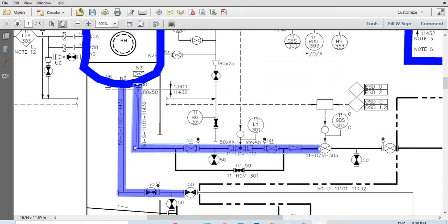And then we have these 2 block valves here and the spec blind. Normally, when you have two valves that are closed, the shading inside is what makes it different, and that means it's closed. When you have 2 that are closed side by side, then we can say it's isolated.